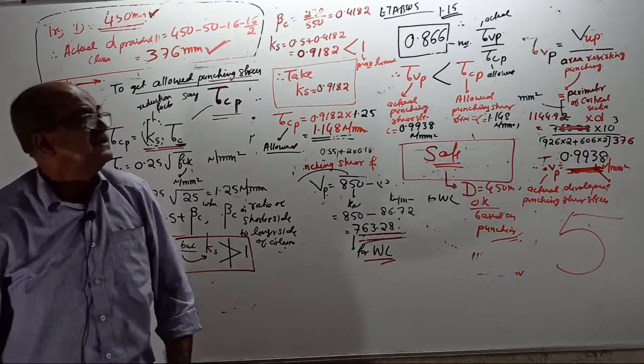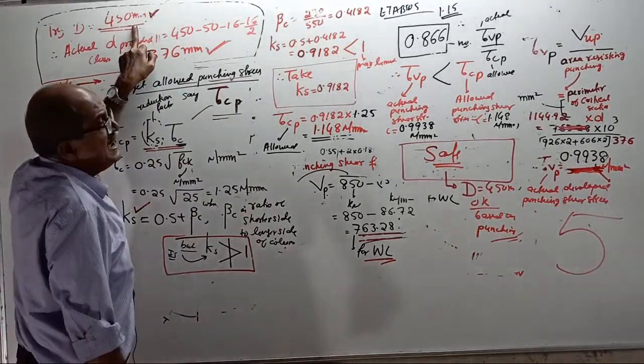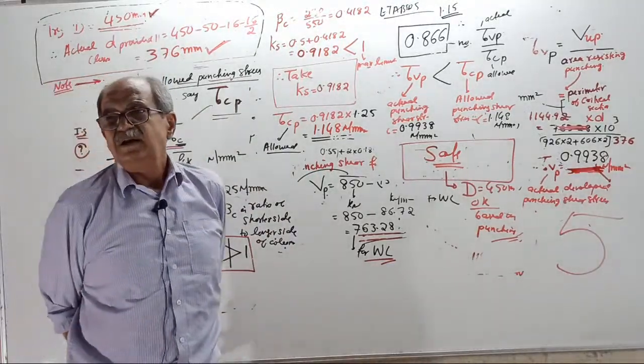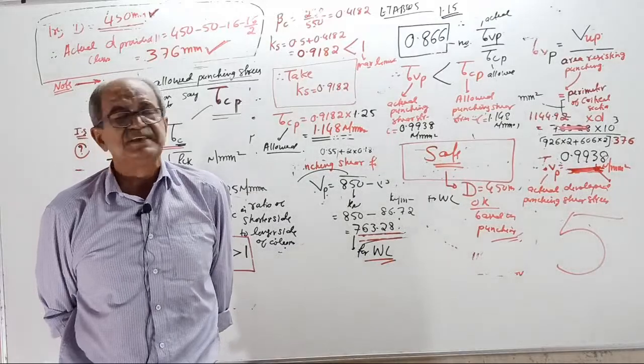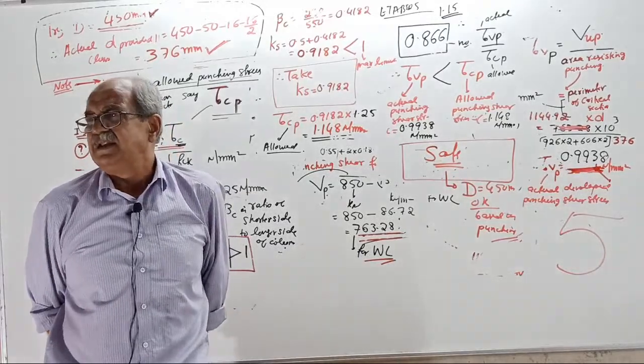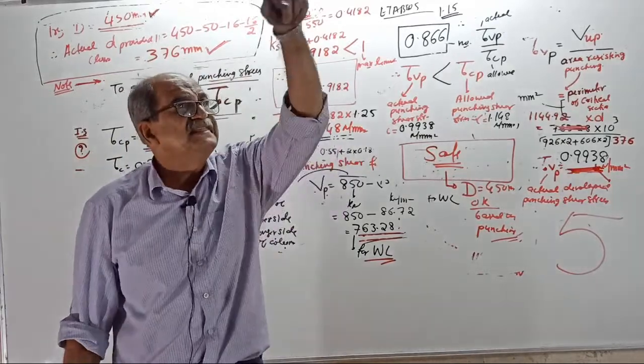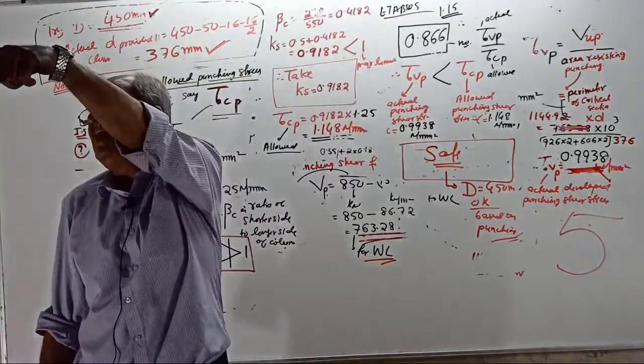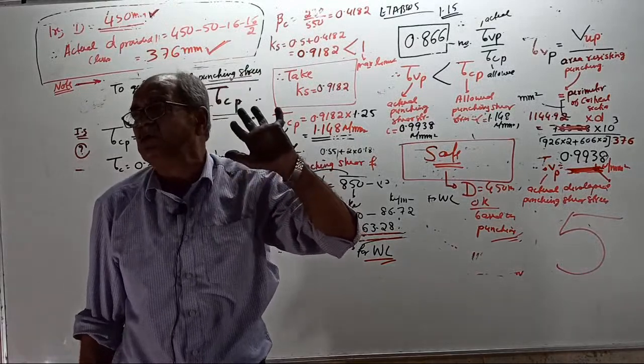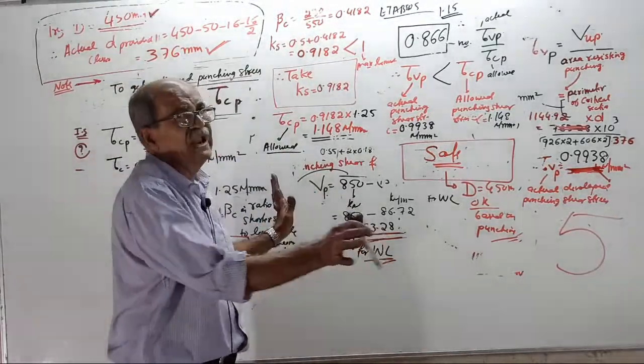15% over stress. Then depth to be increased or decreased? Tell me. Your depth, what do you have to do? You have to edit. You click the model, go to edit and change the depth. That's all you have to do. You don't have to do any calculation.